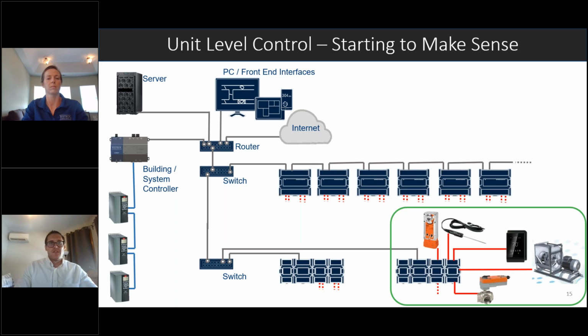With that, you're able to ramp back the energy intensity of your fan, not run it as hard, and drive open VAV boxes a little bit further as needed, so that you're really optimizing that system. So networking stuff together as you do with the BAS system offers those advantages, whereas if they were standalone, you wouldn't be able to do that.